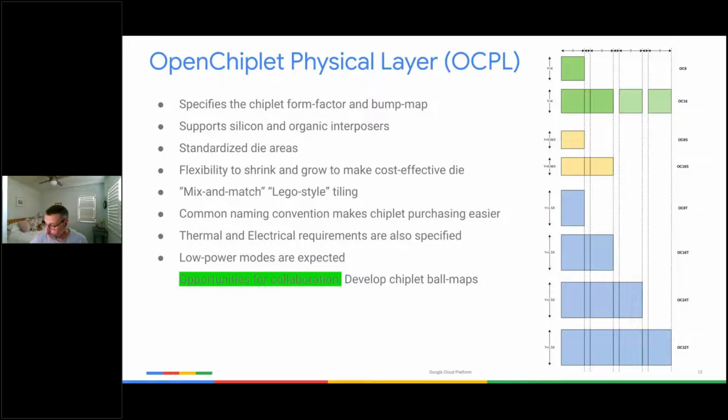If you're abutting the chiplets, you want the die-to-die interfaces to be roughly on the same pitch, or ideally exactly the same pitch. Yeah, that sets one dimension. As you said, you're stamping down your instances of the die-to-die PHY to maintain a certain pitch. But we would still want to control the overall dimensions of the chiplet, by allowing variability in the Y dimension, essentially.